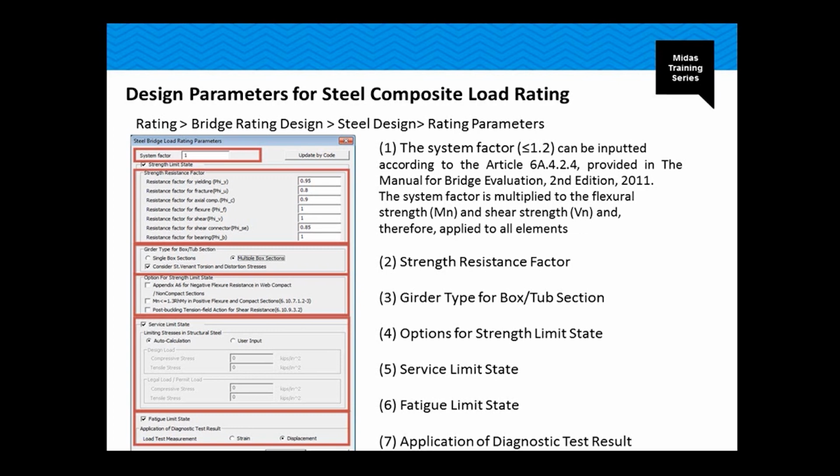Then we have the service limit state. In this case, you can limit the stresses in the structural steel, or you can manually input the design load and the legal load or permit load stresses, limit stresses, whether it's compressive stress or tensile stress.